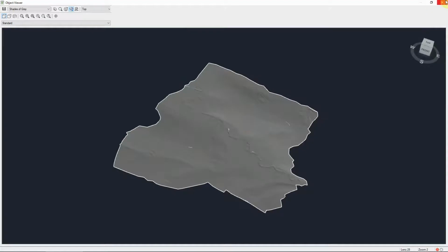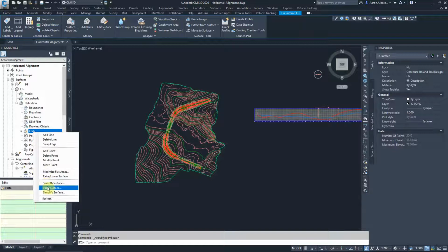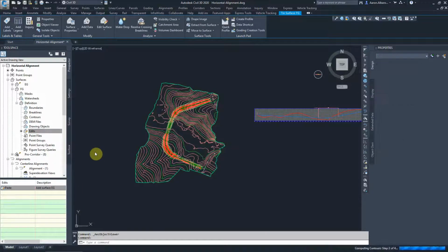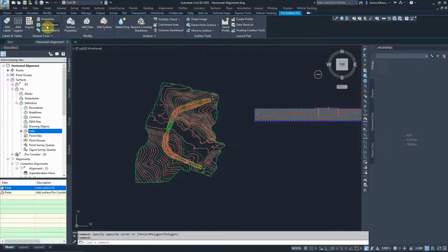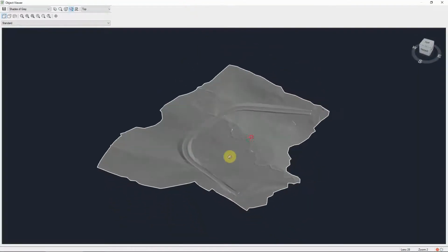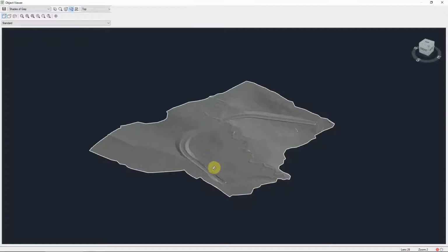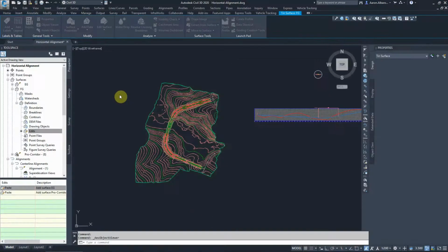Okay, what we need to add into it, another one, paste another surface, which is our corridor surface. Now by adding these two together, we pasted the two surfaces, or we combined them into one surface. So if I look at them now, we have one surface that's showing two components together, or the two surfaces together in one surface. Okay, we combined all of them. That's showing the road here connecting to the existing two roads, and the cut and fill arrangement around our road. Close that.